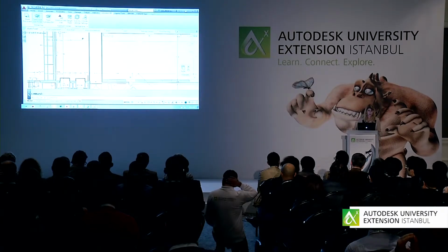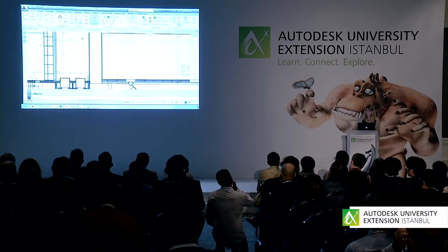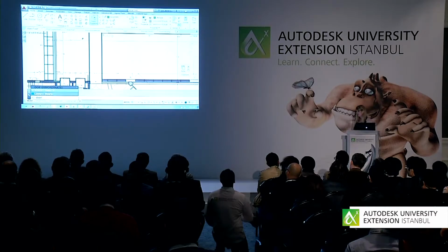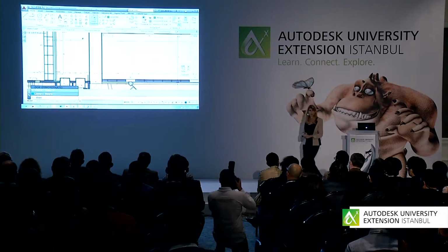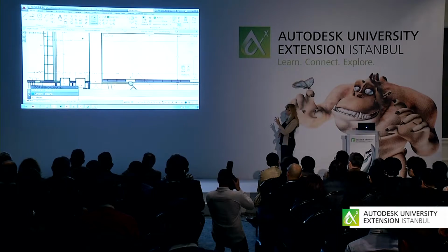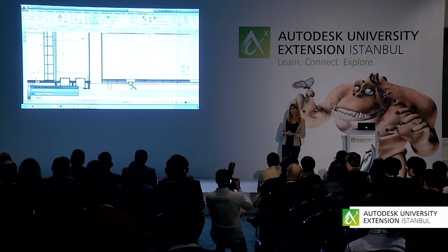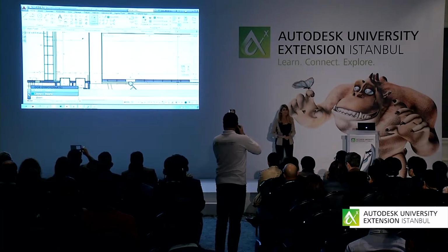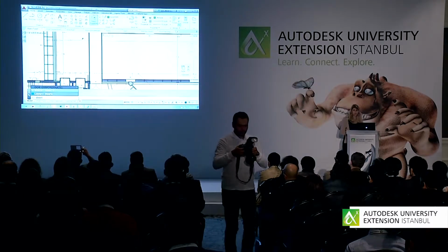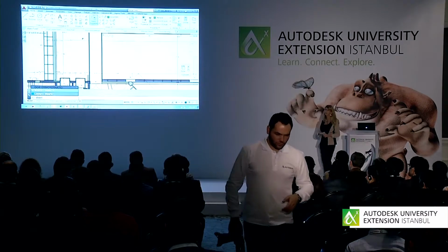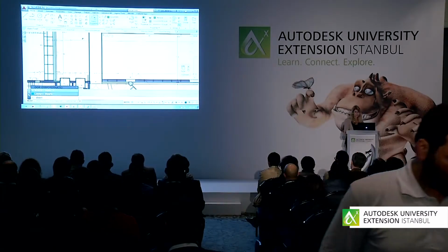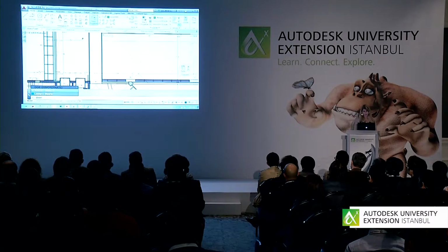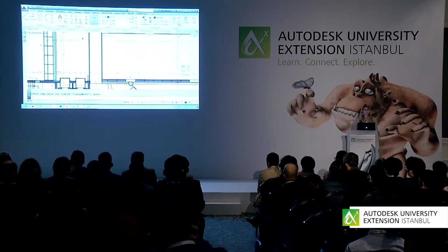You will also find that AutoCAD 2014 or 15 allows you to type in content. For example, there's no command called door, but you'll see that it found a block called door and a layer called door. If I clicked on block, it would insert the door, door 1. Take a look at the current layer in this drawing file. You can see the current layer is equipment at the top. I can actually click on layers doors, and it sets that to be my current layer.